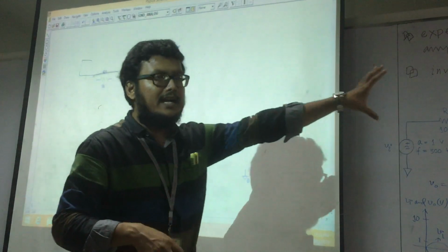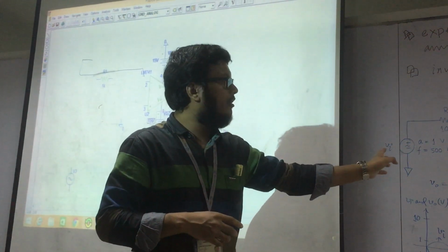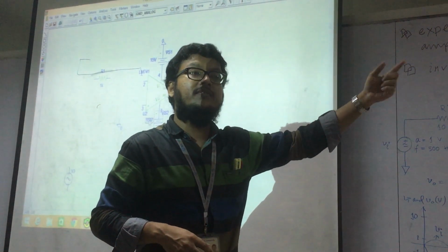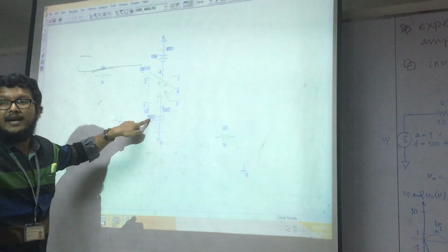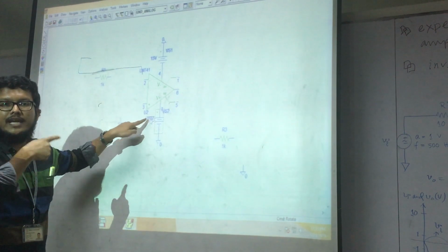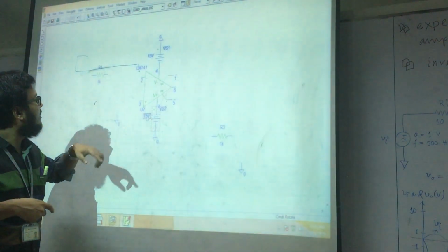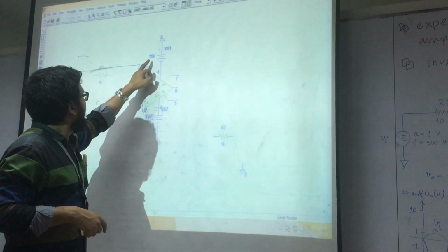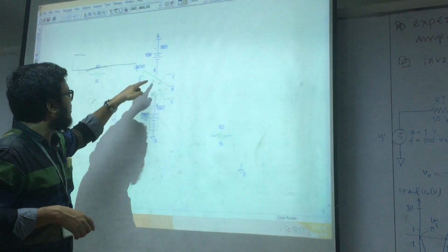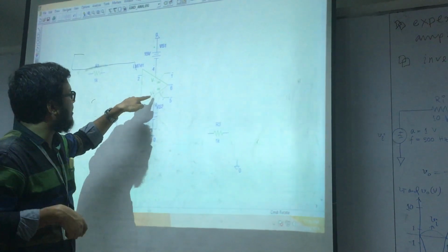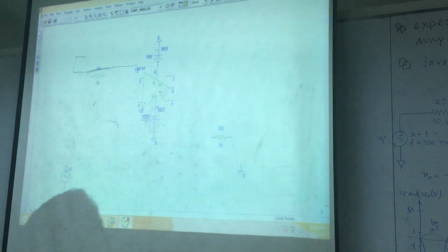If you follow the bigger diagram, which I showed you earlier, both voltages were positive, 15, 15, top, bottom, okay? So 15, 15, don't go for any minuses in here. This is reality, so all positive. So VS1, 15, VS2, 15, but depending on the connection, this guy is going to be negative, the normal voltage, and that guy is going to be positive, the normal voltage.